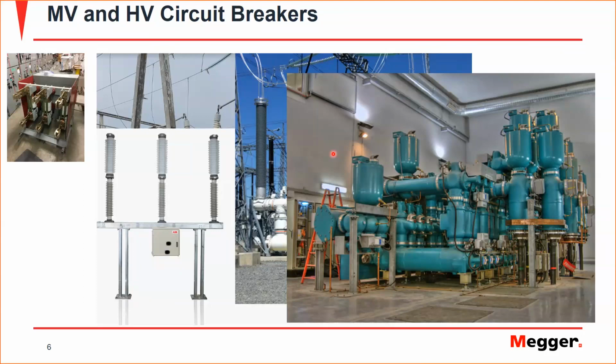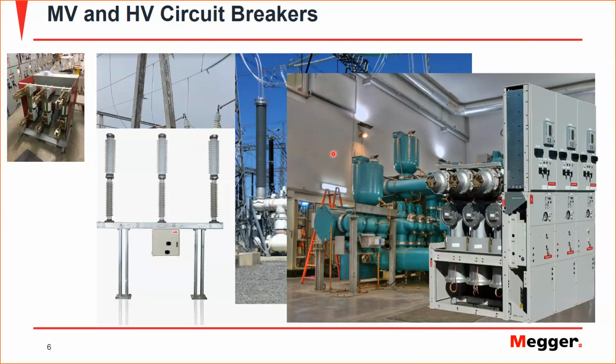And these GIS systems are not only in high voltage substations, as some people might think, but they are also available in medium voltage installations or distribution systems. Their appearance there is quite rare compared to the high voltage, since their cost is much more, and the advantage that they give you is mainly more compactness and a smaller footprint of your substation.